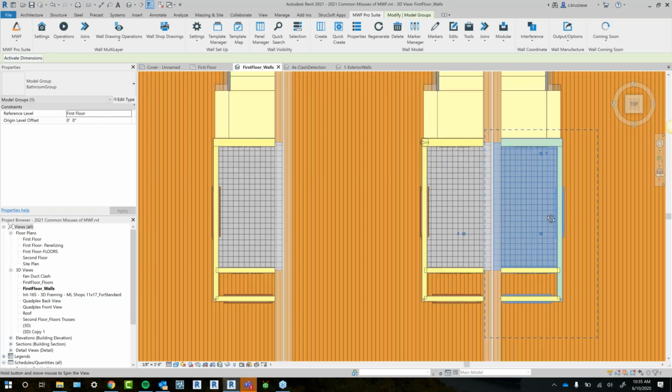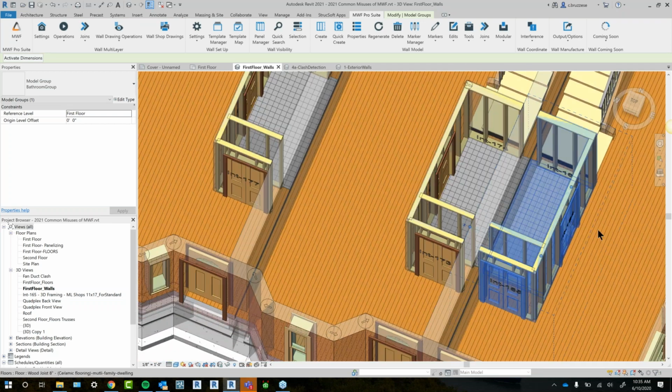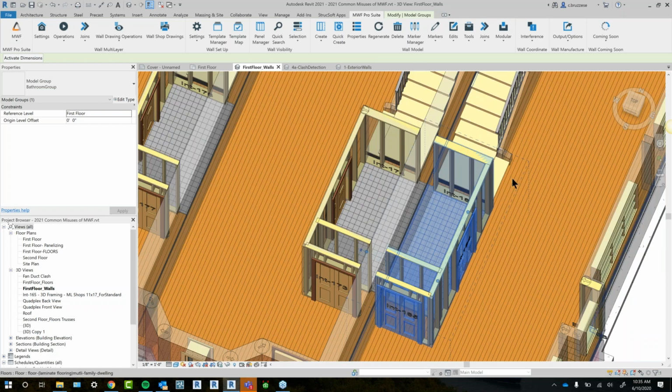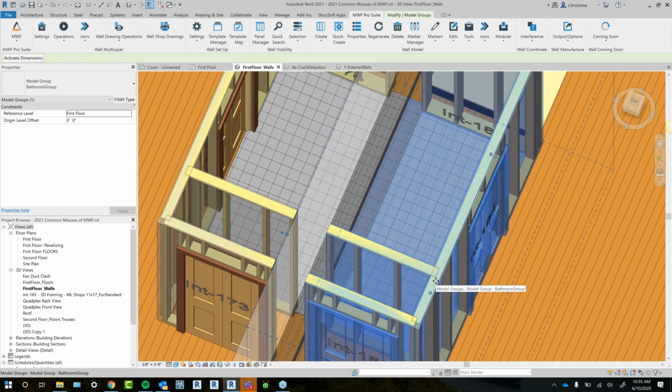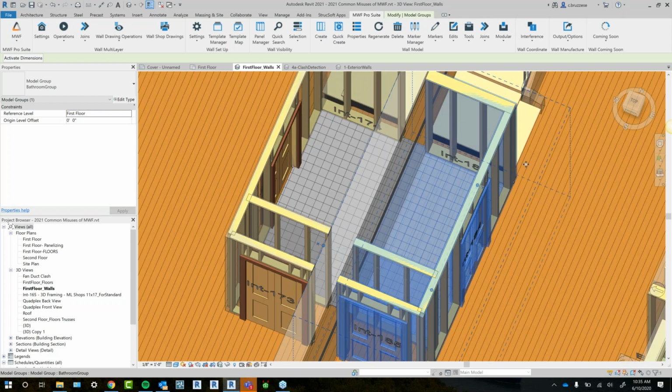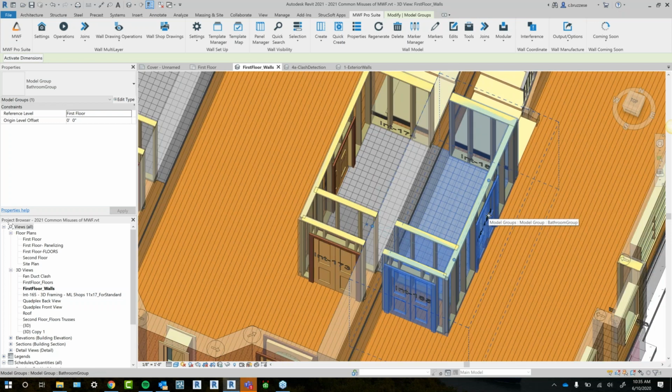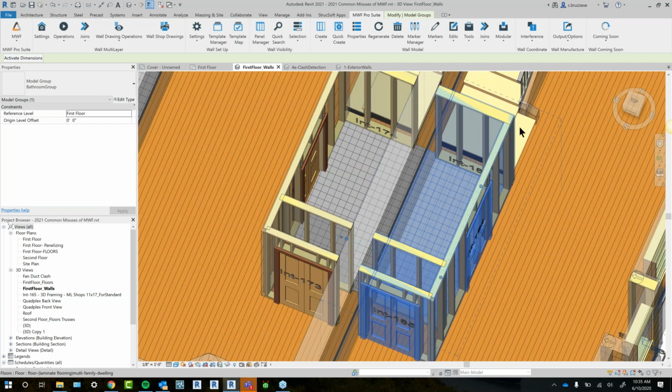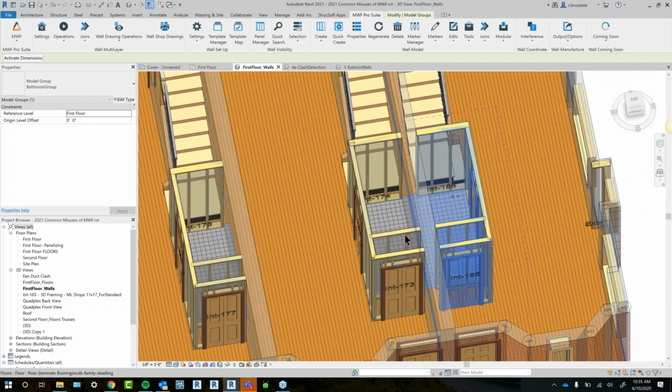And it does apply to your other groups as well. Because there's no join marker here, if you do regenerate this, guys, it'll revert back to the Revit wall lengths. It won't keep your join. But in theory, if you're modeling out one group entirely and it's done, you can copy paste, and there shouldn't even be the need to rejoin them if you do most of your changes in one group.